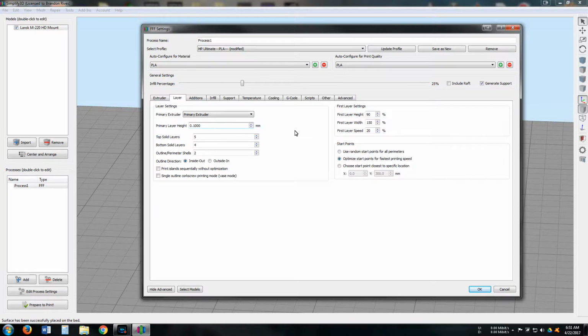So basically the printer pretends like it's doing this, but the nozzle height away from the bed is actually only 90% of it, which in return will push the filament down on the glass plate harder in hopes that it will stick better.